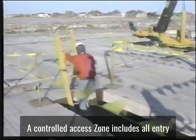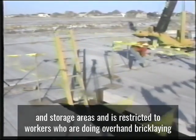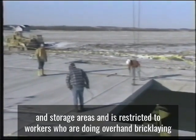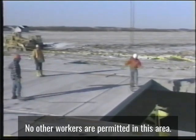A controlled access zone includes all entry points, as well as materials handling and storage areas, and is restricted to workers who are doing overhand bricklaying or other leading edge work. No other workers are permitted in this area.